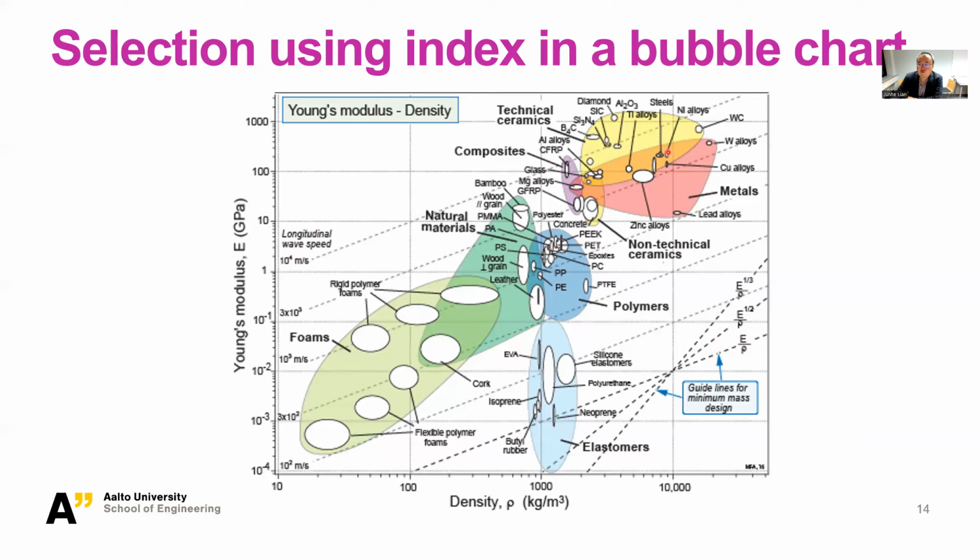And what you should notice, an interesting fact, is that here we're looking at steel, and here at aluminum alloys. They are usually competitors in the market. Roughly speaking, the densities of these two materials are very different, as well as the stiffness. But actually their specific stiffness, basically E over rho, is almost the same. Very interesting.